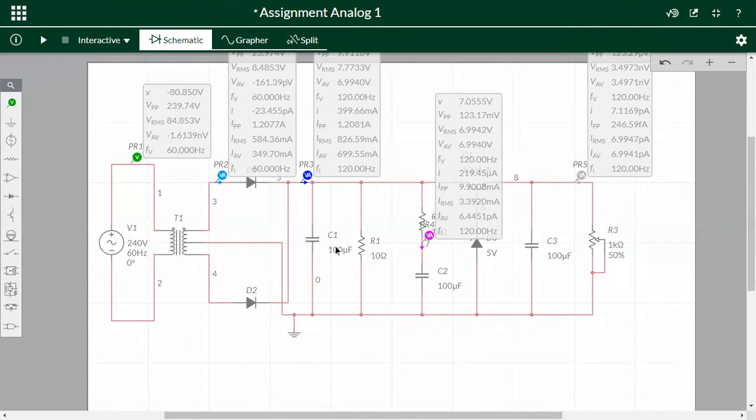The capacitor has a highest charge at the quarter waveform in the positive half cycle. At this point, the voltage supply is equivalent to the voltage of the capacitor. Once the AC voltage begins falling and becomes less than the voltage of the capacitor, the capacitor begins discharging gradually.